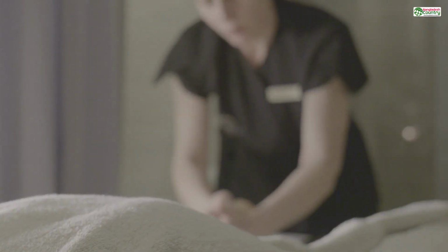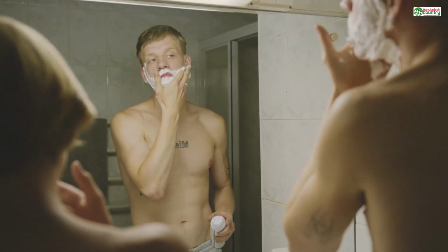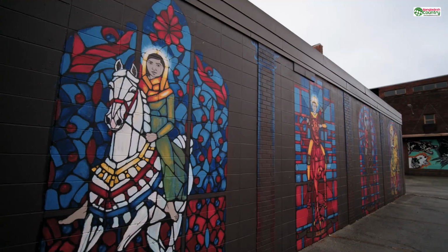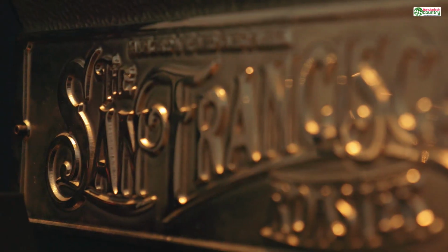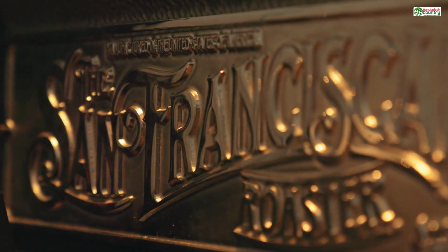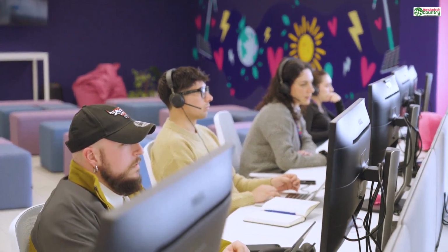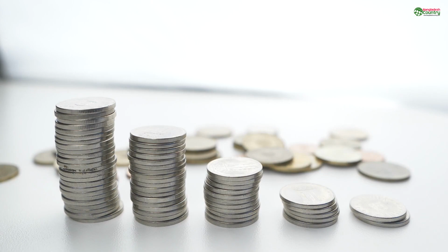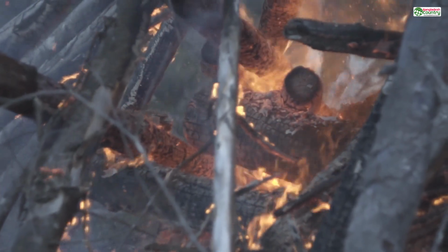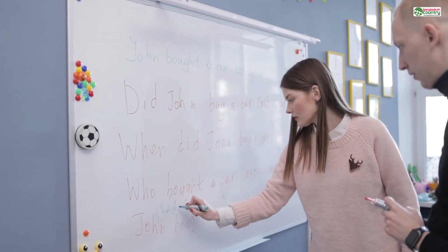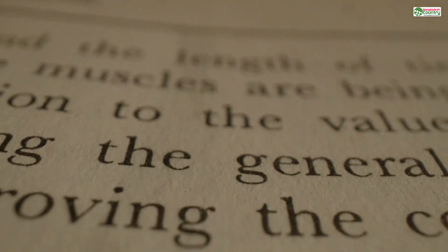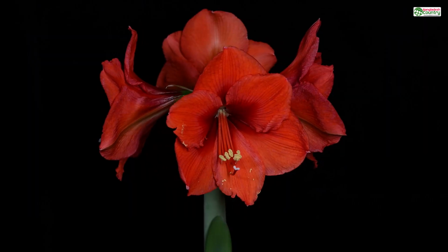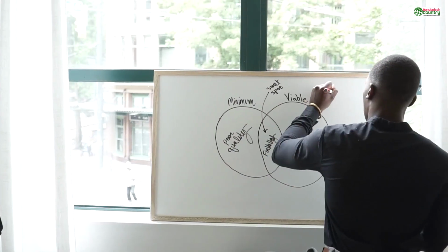You'll also learn to distinguish between structural thickness and surface detail. The main wall of a box needs to be structurally sound, say 2 millimeters thick. But text you engrave into that wall can be much finer. The service's design guide will often list a separate, smaller value for minimum detail size, or embossed/engraved details, which might be as low as 0.2 or 0.3 millimeters. This is because those details aren't holding anything up. They are fully supported by the thick wall they're attached to. Understanding this difference allows you to create highly detailed models that are still incredibly strong.